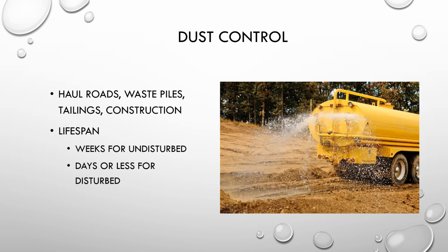And so it depends on the application, but it's a very effective way to decrease your water requirements when you are keeping dust down. If it's not on a roadway and you're applying it, it's going to aggregate those soil particles and hold them in place. And so that also likely won't need multiple reapplications.